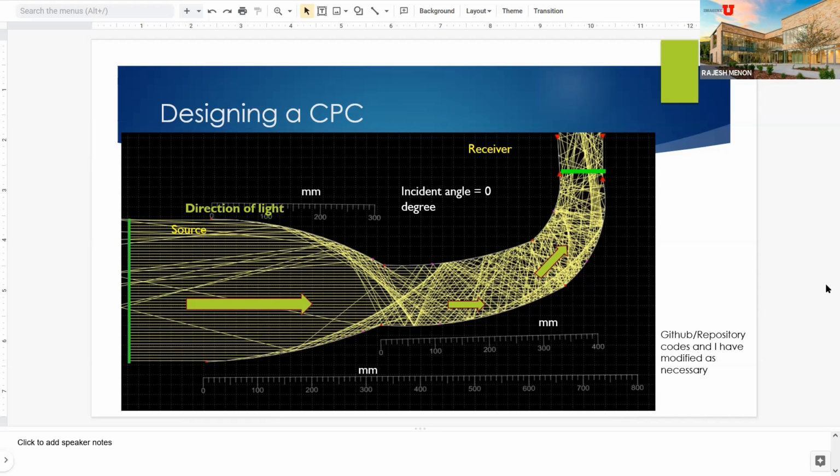Below the monitor, there are two small pink dots, and from those two pink dots, it's the optic fiber that is carrying the light. It's not simulated up to infinity, but for simulation we have to define a model, so that's the end of the model. We can see that for 0-degree angle of incidence, we are receiving approximately 63% of power.